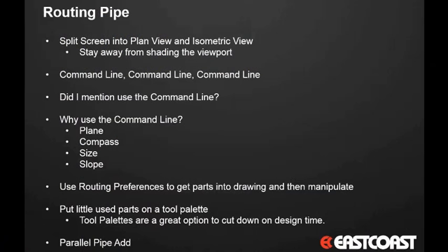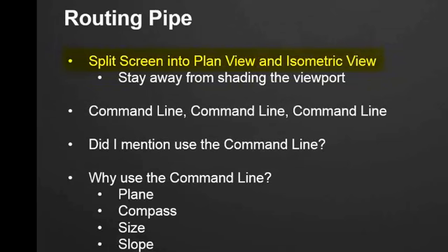So today, routing pipe. One of the first things I would recommend to you is to go ahead and split your screen into a plan view and at least one other view, preferably an isometric view. That will give you the ability to see your pipe from overhead and then also in a 3D view.